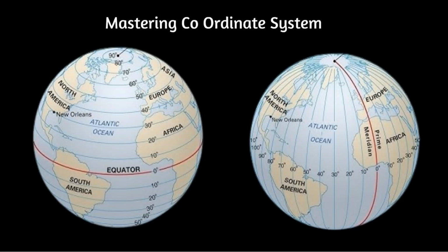Northing, that is the y coordinate, is used to measure distance north or south from a reference point. It may be from the equator or generally from a baseline used for every project. These values are typically measured in meters and are part of the Universal Transverse Mercator or state plane coordinate system.